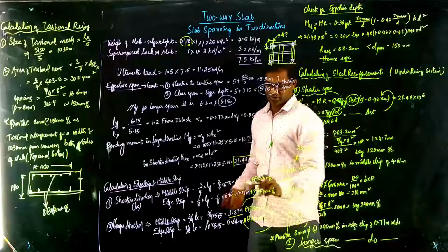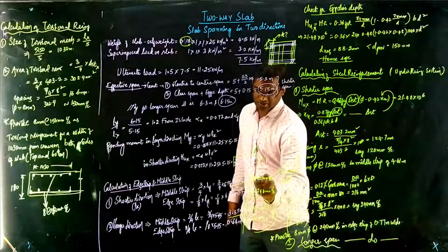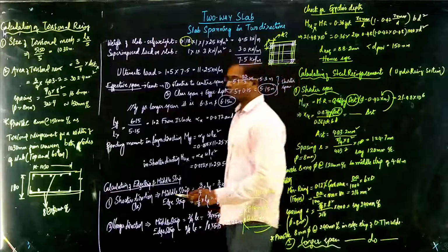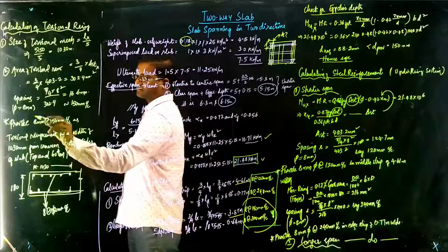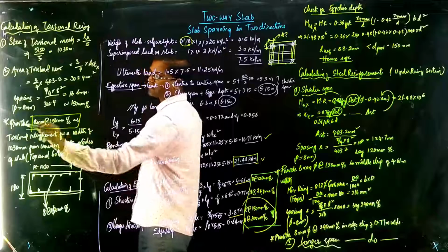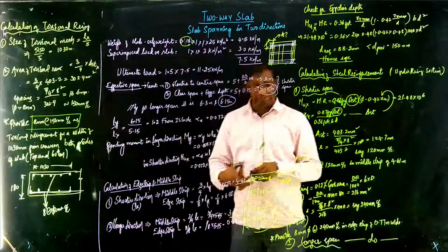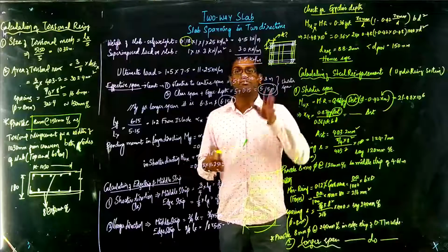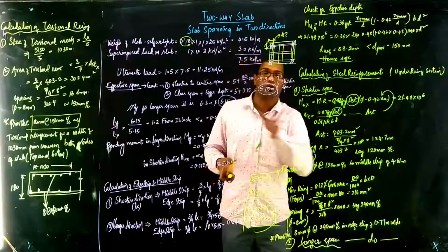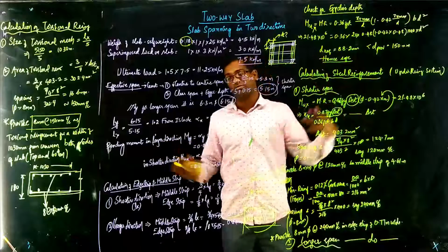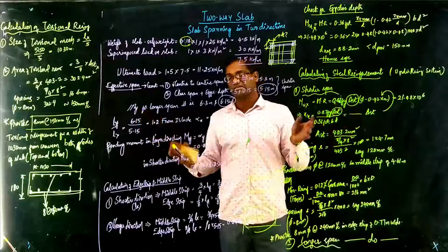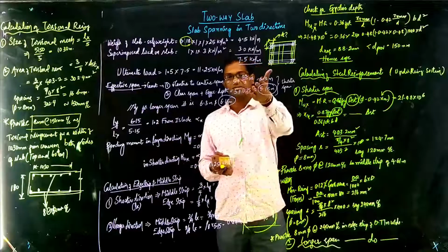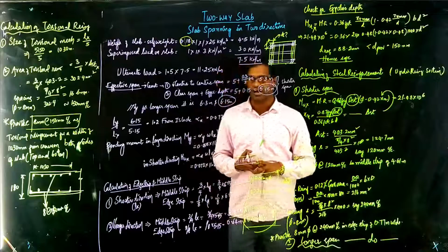So for the time being, remember this: how much is the middle strip values, how much is the edge strip, and also you need to remember this value which is provided as torsional reinforcement and some of the conditions which are stated, because if you are providing middle strip, the middle strip reinforcement should go into the edge strip, edge strip should come into the middle strip. If it is continuous, there are certain value strips. We will discuss all those things, the stipulations which are provided in the code for the slab, in the next class.